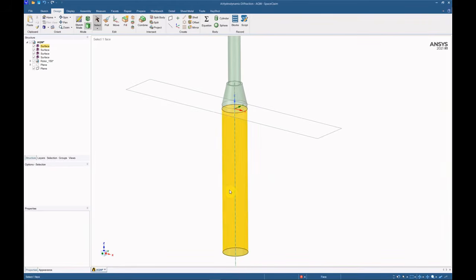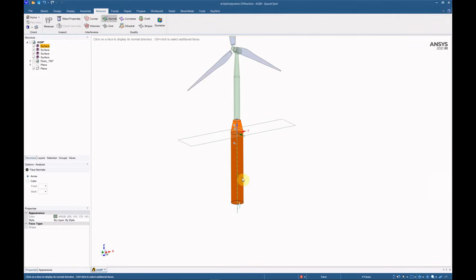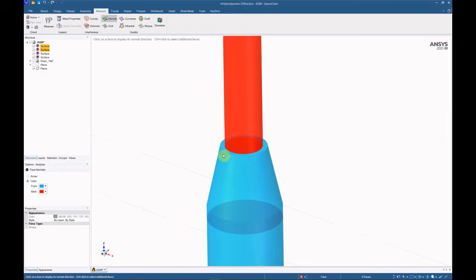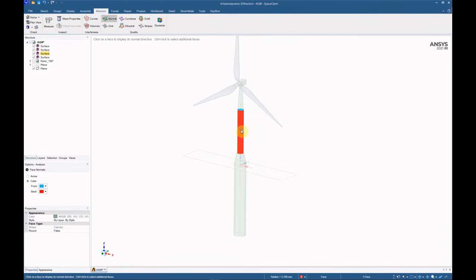It is good to check that the surfaces of the hull have normals pointing outwards. This is to ensure that the hydrodynamic model does not fail to calculate the hull displacement. If they point inwards, the calculated volume will be negative. As an example, if you need to flip any of them, right-click and use the Reverse Face Normal option.